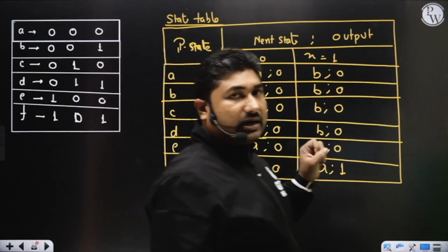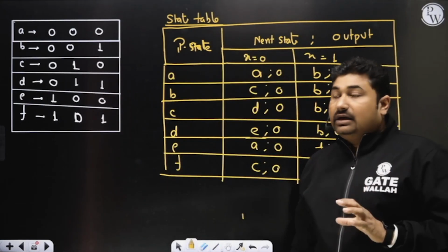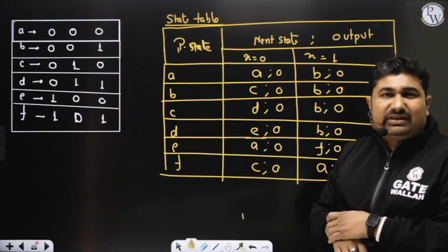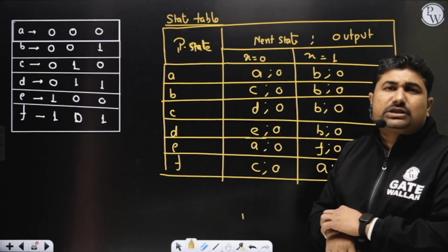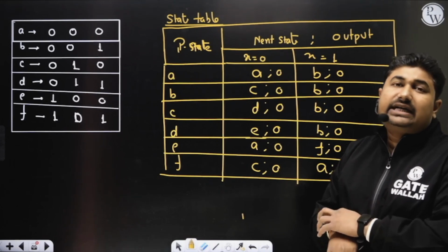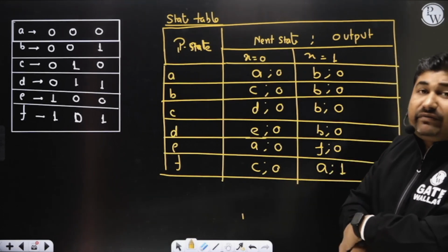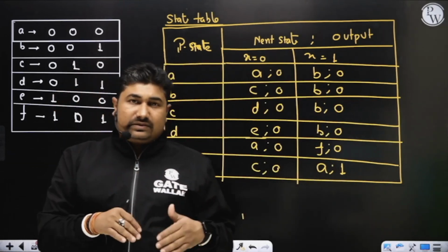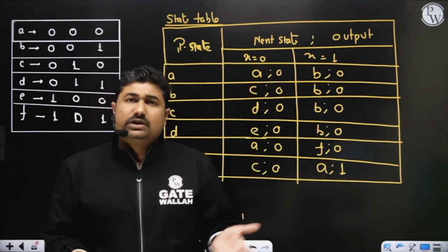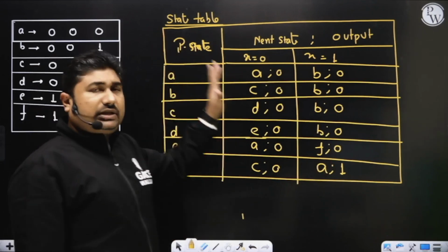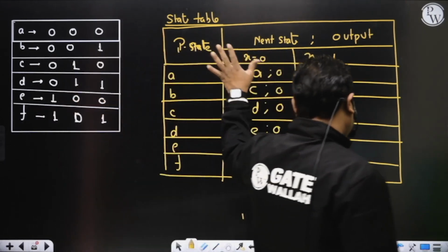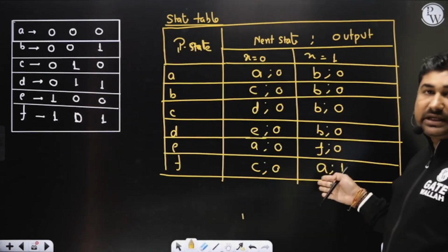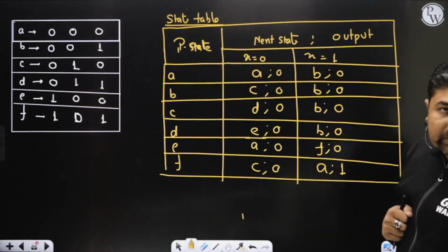It helps us to understand whether any redundant state exists or not. Since we have designed in a proper way, there is no possibility of a redundant state. Redundancy is only possible if we are not analyzing all of the states. Since we know the sequence, we have designed in the same fashion. So there is no redundant state. We have to go with 3 flip-flops. Is it okay? Now this table helps us to find the excitation table.